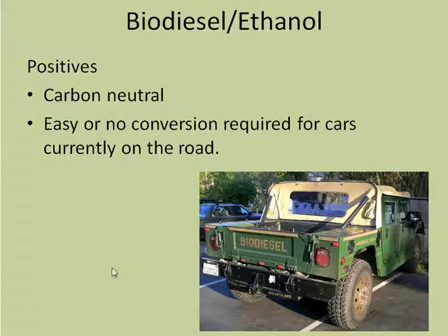So with a lot of vehicles, depending on what rate you mix the diesel with the lipids from plants, the oils from plants, you can put it straight into cars that are already running on diesel. So you don't have to do any conversion. You can do it with a slight conversion with your injectors so that they don't gum up. You can pour chippy oil straight into your tank, with filtering out the little bits of chips, of course, and burn that and drive down the road. And I've heard that those vehicles actually smell a bit like a fish and chip shop.